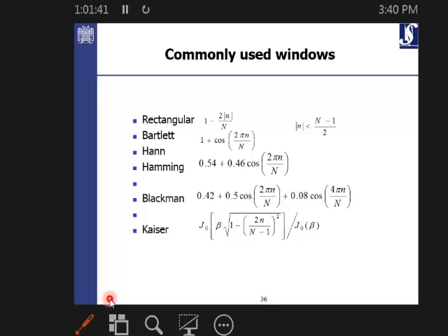One of the other approaches for designing the FIR filter was the windowing method, and it's quite similar to the idea of impulse invariance. We just take one of the windows and take the samples out of that. So any of these windows will give you h of d, which is this window times the ideal filter that you need.